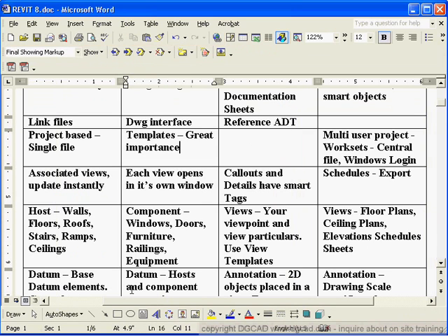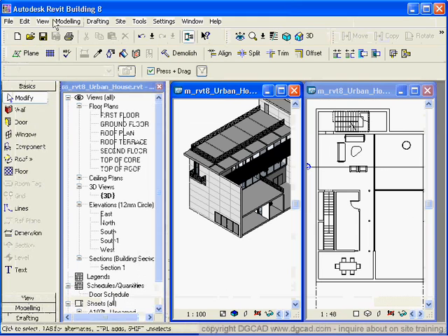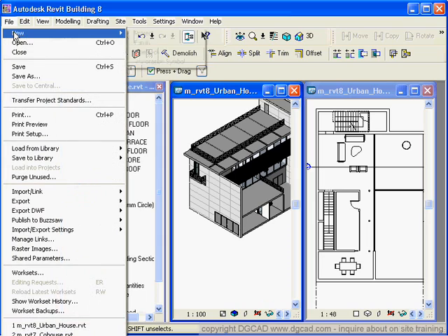Let's go back into here and check our notes. So when I'm going to start a new file, I'm going to show you where you can get a template, and we'll just see where that is inside. So if I go up here and go File and say New, it's going to say, what do you want, a new family, which is a bit like a block, but it's more universal because it will sit on the server or on your hard drive and it gets pulled into your drawings. I can create a new title block specifically, which is its own little kind of environment. An annotation symbol, if you want to create your own symbols and annotation objects, you say File, New here.